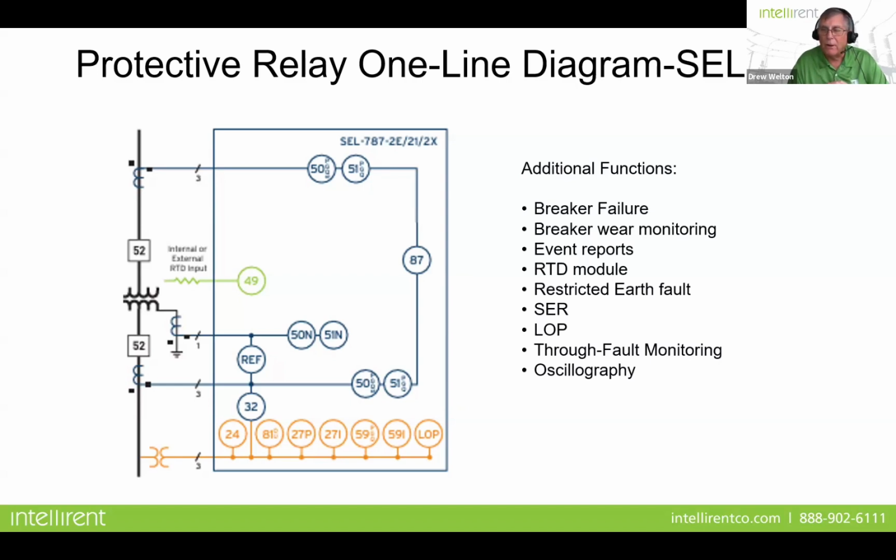Well, my very first question was, okay, can you send me your sequence of events record and your oscillography that the relay captured? And then it would go quiet for a minute, and then I'd get, well, we forgot to enable that in the relay. And I'd be like, can't help you. There's not much I can do in terms of help diagnosing the problem.